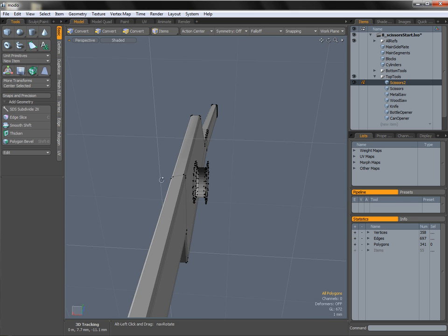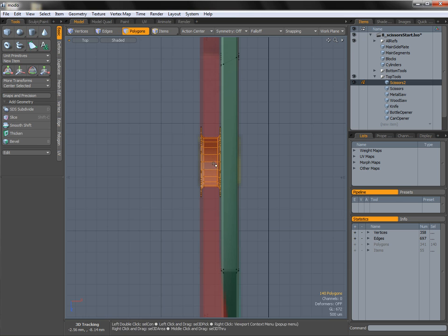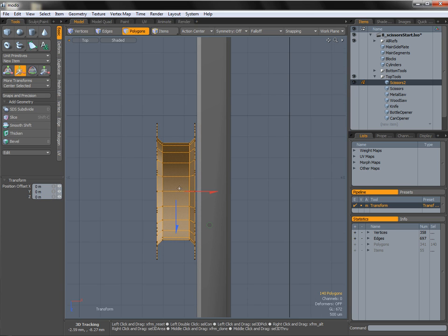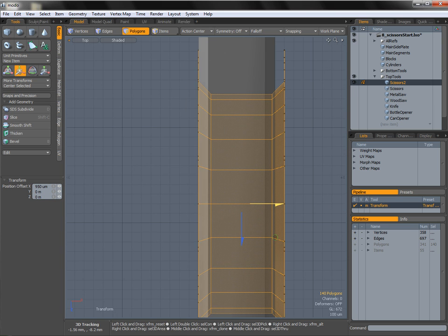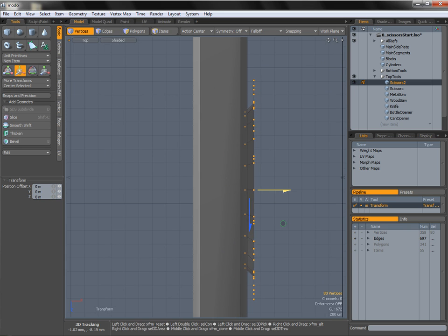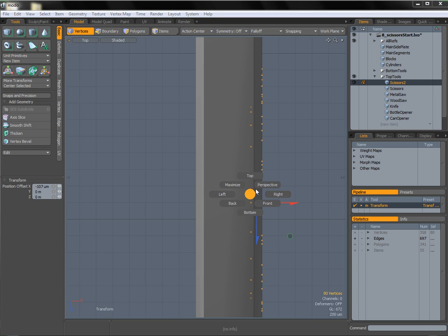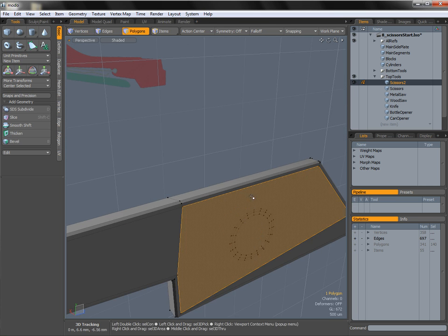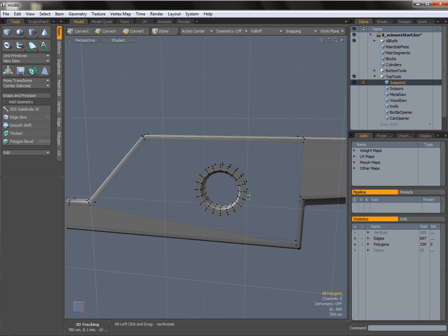Now obviously these 2 objects are slightly offset, so we're going to have to move this into position. So I'm going to go into a top view and I'm going to move this like that. So we line up one side with the outer edge of our scissors object. Then I'm going to lasso select these verts and move these into position on this other side. Zoom in really close if you want. So something like that looks pretty good. Go back to perspective. I'm then going to delete both of these giant polygons, and we can go about kind of connecting these guys together.